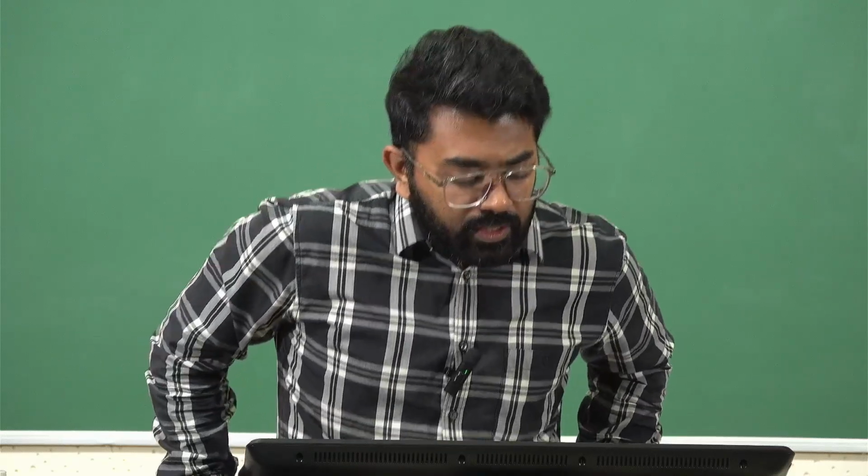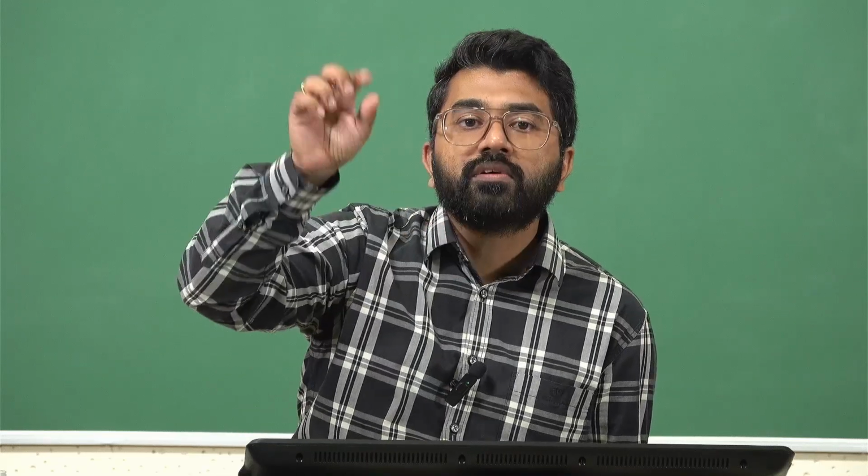So hopefully these terms are clear: what force is, what displacement is, what stress is, what strain is, and finally you describe it using a plot. You have to just run an Excel or a MATLAB program to quickly divide all these terms. The displacement and the forces in newtons is what you will get as the output from the UTM machine, and you are going to do the post processing. Some of the machines have auto calculation, where it will ask you to enter the area or the initial length, and it will auto divide it and give you the stress and strain only.